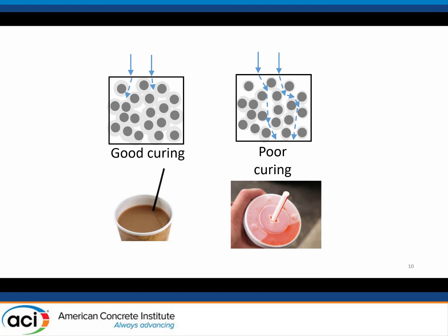Now, some of you are drinking coffee. I see you. It's early in the morning. I get that. When you drink coffee out of one of those very thin coffee straws, you got to work real hard to get that solution up. And that's good because you don't want to burn your mouth, right? And that is like good curing. And the system on the right, that is not so good curing, and that's like those big McDonald's straws. You know the thing you can drain a cup in about a second if you pull on it really hard? And that is what poor curing is all about.